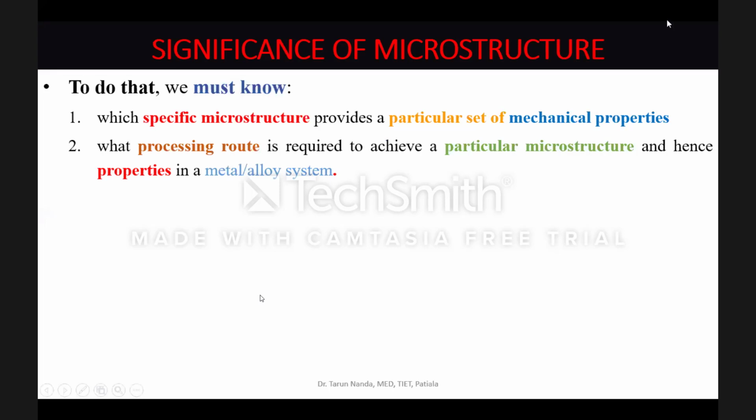Mechanical property is a property whose magnitude depends upon the response to the load or the stress applied to a material. For example, hardness, you provide a point load and the material under the effect of that point load indents. And then a material which indents more gives less resistance to indentation, possesses low hardness. The other material which gives more resistance to indentation possesses more hardness.